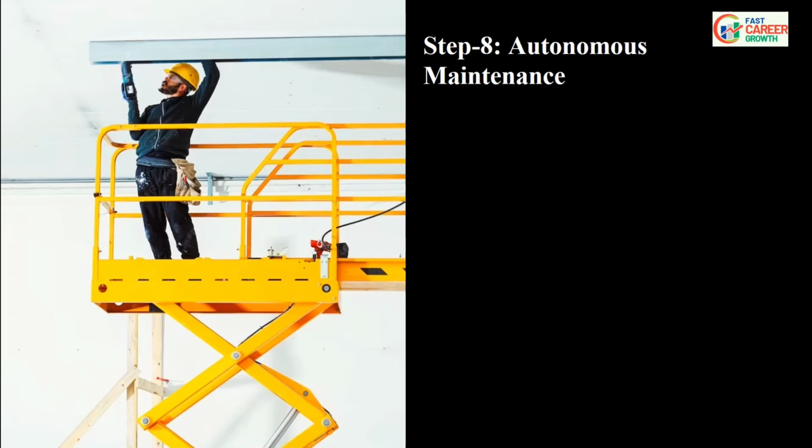Operators in autonomous maintenance are responsible for tasks such as cleaning, lubricating, inspecting, and tightening. A clean and organized workplace is fundamental as it enables us to spot abnormalities and prevent equipment breakdowns. This step is pivotal in TPM and involves empowering operators to take responsibility for the care and maintenance of their equipment. It aims to reduce equipment failures, improve reliability, and create a proactive maintenance culture.